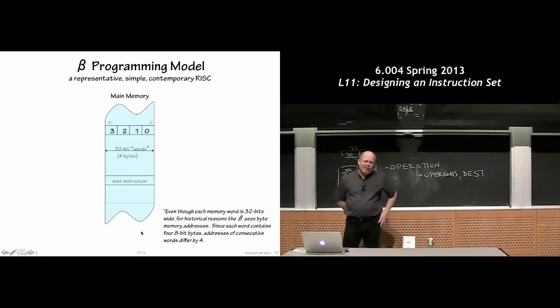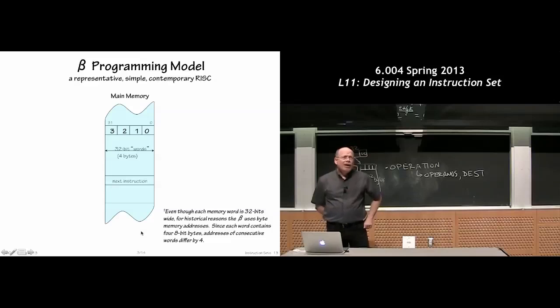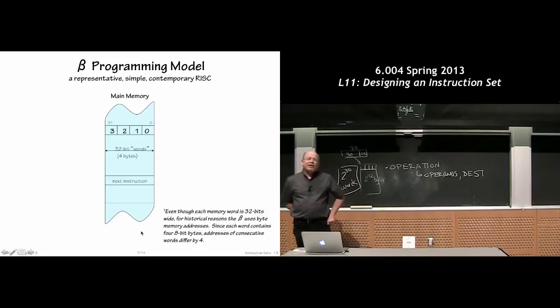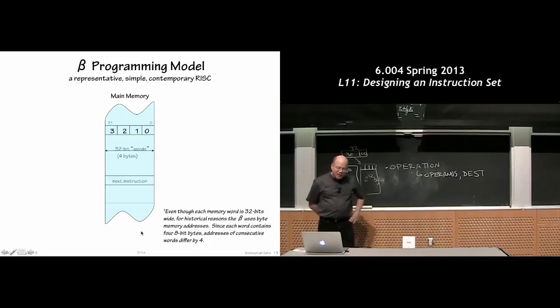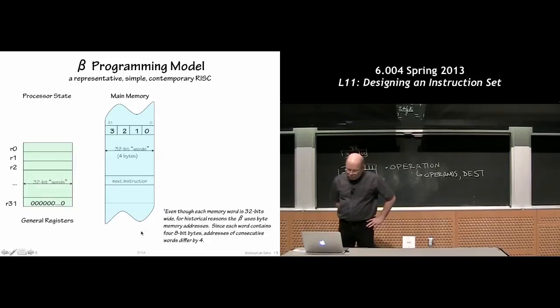And you can say, why are we doing this, Chris? This seems very complicated. Couldn't we just do a word address memory? Well, this is all sort of lost in the mist of history. We're trying hard to be compatible with machines that you're likely to see, which almost all support some level of byte addressing. So we've adopted byte addressing as our convention, but we're only going to use it to address words. So the bottom 2 bits of the address will always be 0.